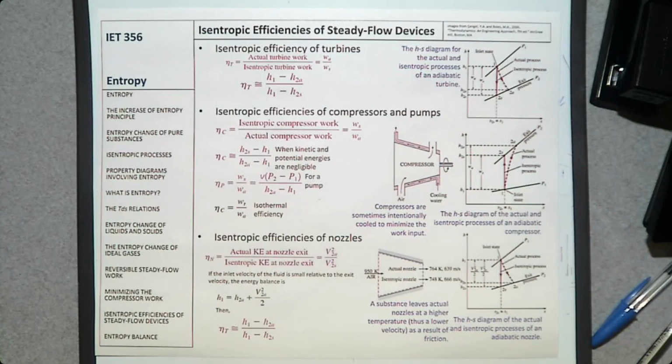You will see isentropic efficiency, whether it is given or whether you need to calculate it. We haven't studied isentropic efficiency yet. The previous problem was about whether you can calculate entropy change in an isentropic process by using the simple specific heat equation.